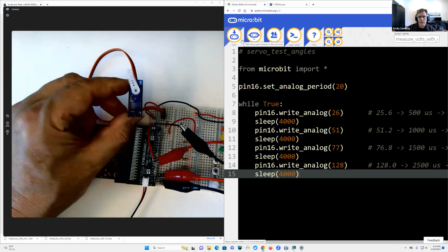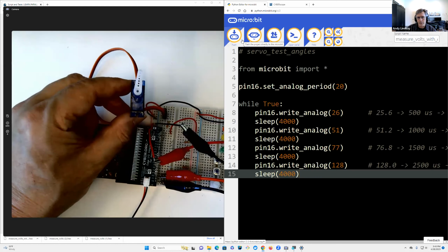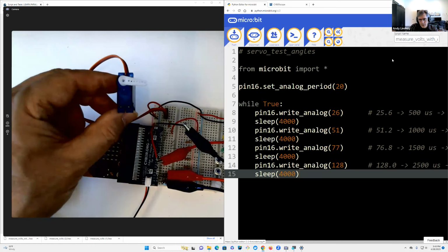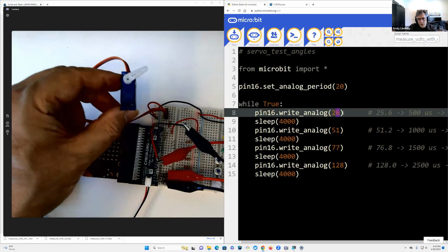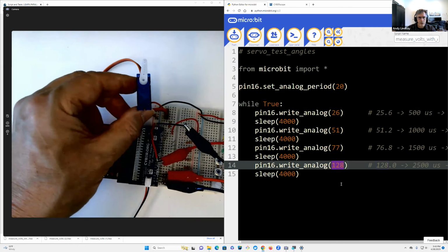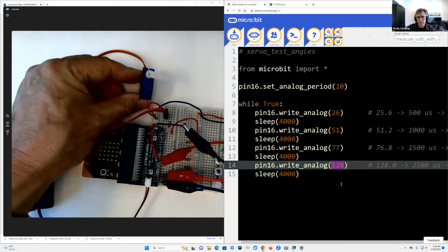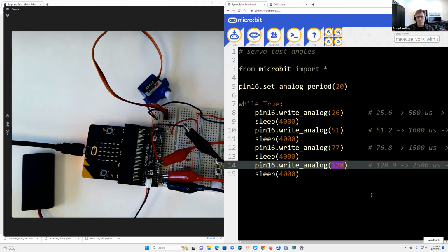And you could actually, I think I might on this one, just take the horn off, and if I wanted to be a little bit more precise, I'd take the horn off and rotate it by maybe one tooth on the little shaft that it's pressed onto. And then I might also adjust the values in this script a little bit just to get that 128 to go to exactly 180. There's a little trial and error for students who like to have things be super precise. But I think that's a good first cut.